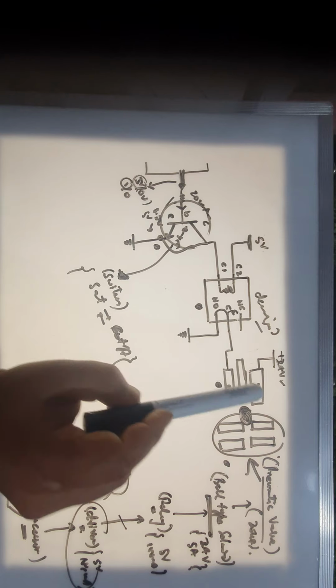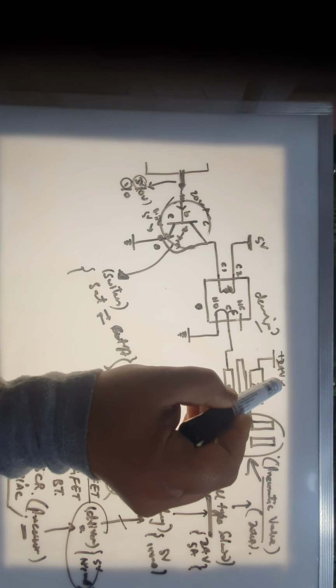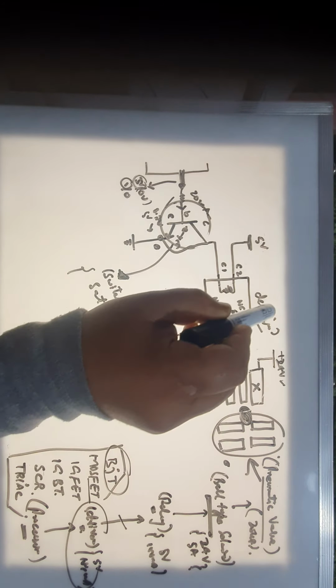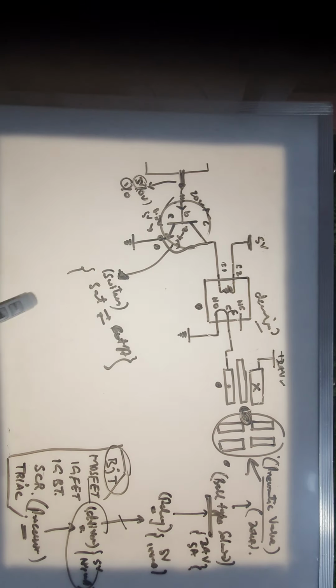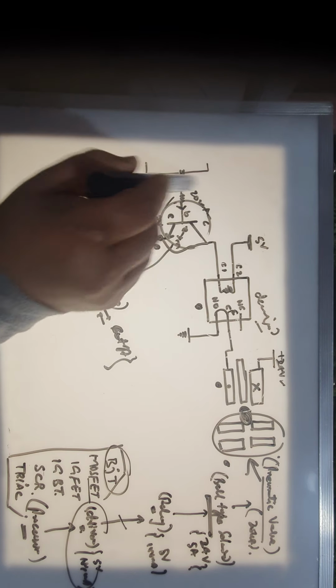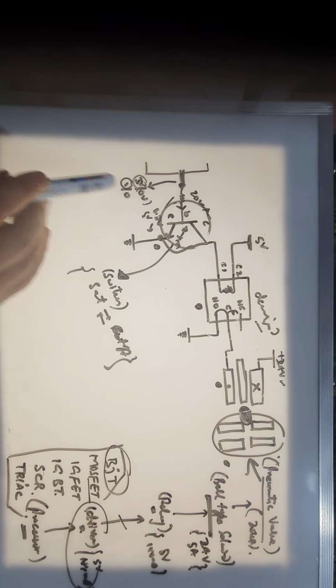So are the other things. The solenoid valve is also going from state 1 to state 2, the relay is also going from NC to NO, and the transistor is also going from saturation to cutoff. All of them are working in a two-state manner, so there is nothing continuous. You may have things where you will have to go continuous also, so that will be taken in some other lecture.